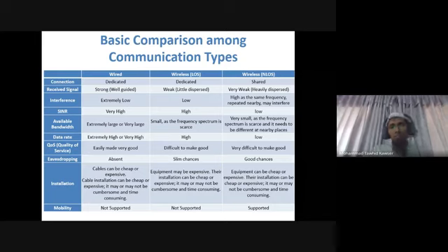So you heavily disperse deliberately from the transmitting end. When you disperse your transmit power, the density will not be that much. All the users will receive the signal, but the signal level will be weaker. That's why I gave the example that you may receive just one billionth of the transmit power.